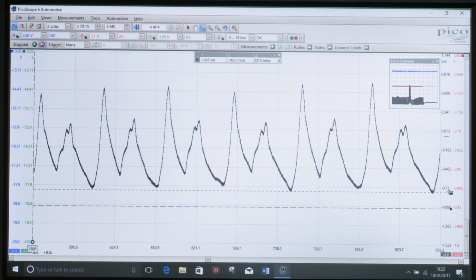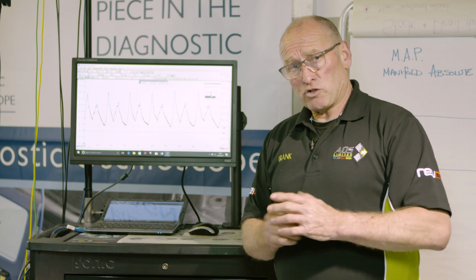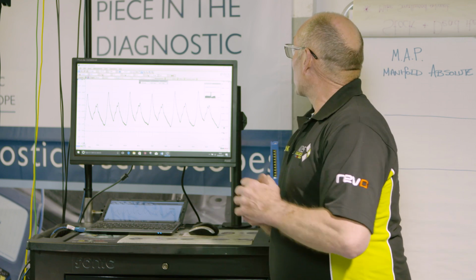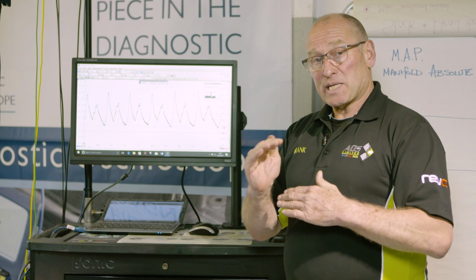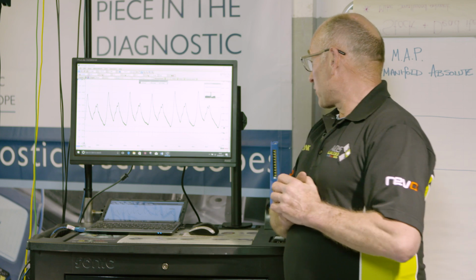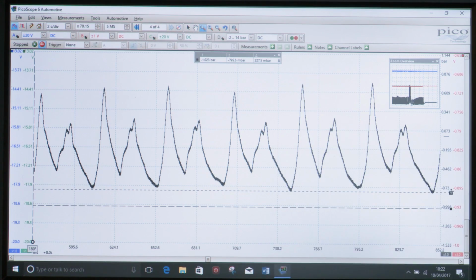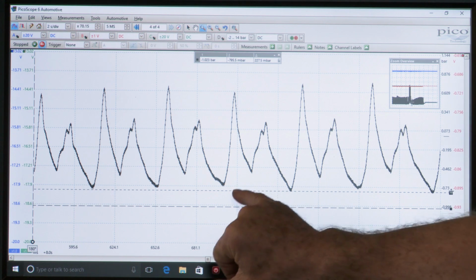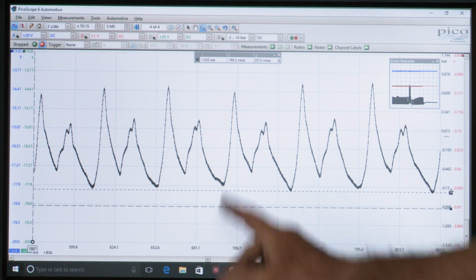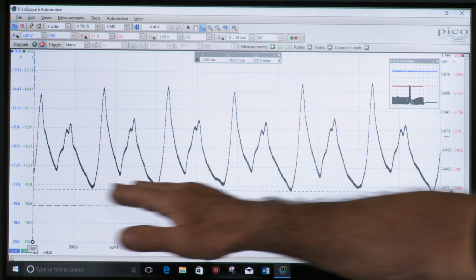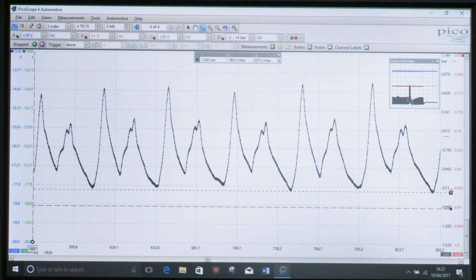Pull that down there. That's 227 millibar. Now I said 300 millibar is a good figure that you'd normally use on a gauge. We're 227 millibar, closed throttle, high engine speed. That is a good figure, proving that the cylinder is sealed during the intake stroke, because this is the intake stroke before compression. So we have a good cylinder. And you could say that that event there, it's the same cylinder we're looking at, of course, so there's a slight difference with that event, but pretty much they're all of much the same figure, and 227 millibar is a good induction figure, very healthy figure.